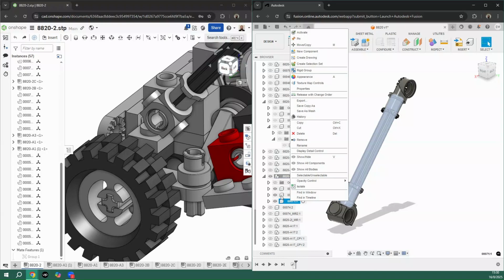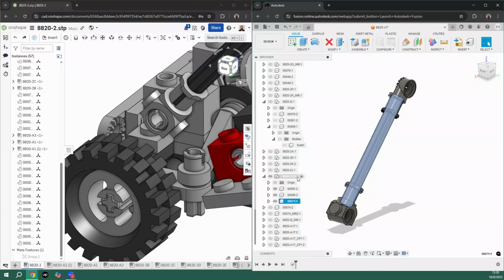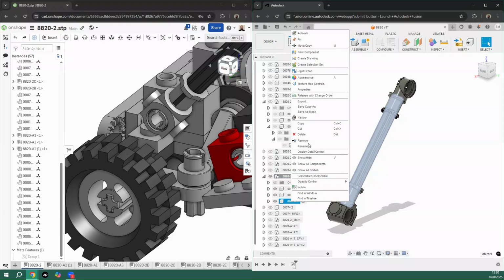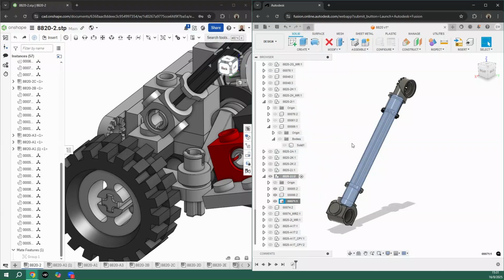Okay, so for this one, I'm pretty sure I'm working on the assembly, on the subassembly, because I have this point on the circle. Now I'm going to right click and click on the option is ground, I believe. There you go. It's the spin. Okay, so this one, internally in this subassembly, is totally fixed in place.